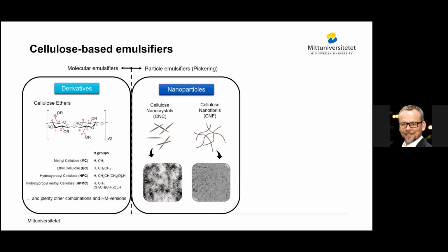Cellulose nanofibrils work a bit differently, but they also have this, but they are so much bigger, so it takes too long usually to get them into the coverage state, since the diffusional processes are slow, but they still contribute, and they also of course change, for instance, consistency. I mean, you get into completely different viscosities and rheology properties, which makes the emulsion work.